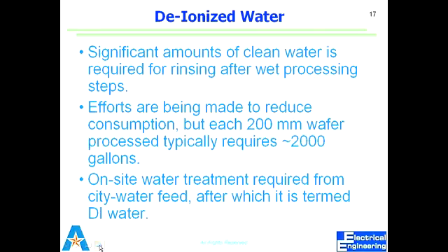It depends on throughput and the quality that we want. The throughput is probably more important. Many times in literature, you'll see water written as 18 megaohm-centimeter water was used. So it's a measure of removing ions, right? Because pure water is, what do you think? Pure water is conductive or not? Not conductive. At 18 megaohm-centimeter it's very resistant. So pure water is not conductive.